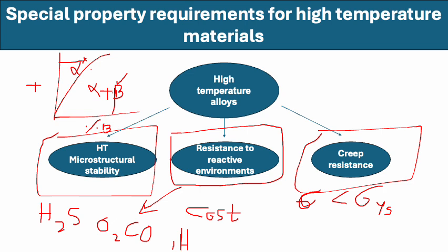So microstructural stability is very important for high temperature environments, because microstructure can evolve quite strongly, because diffusion is very fast at high temperatures. So we need to be careful and consider high temperature microstructural stability. And there is a link between these two, as we will see. The surface reaction to the reactive environment, in the form of either oxygen or steam, can consume certain alloying elements, and it can in turn affect the microstructural stability. So you chose a material that was here. The operating temperature was here, so you are in the two-phase region, you have enough precipitate, you feel happy.